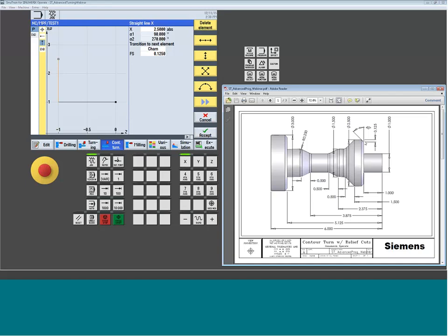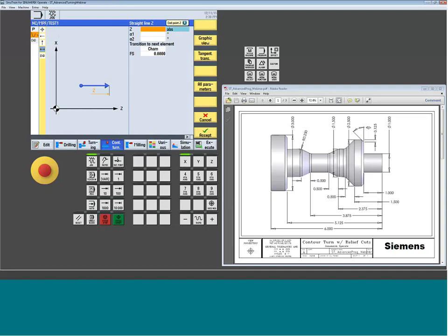Okay, so I started at this front center of the part. I machined back on the boss of the hub. I machined out, I'm right here. Once I get there, I'm then going to come back, and we're going to keep moving around. So I'm out at the 2.5-inch diameter. I got my chamfer. Oops, went too far out. Now I'm going to move back. In this case, right off the print, I'm going back -1.5. Once I get there, we're not putting any kind of chamfers, so we're going to accept it.